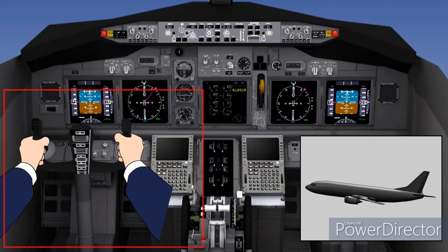The autopilot cannot be engaged on the ground and used for the takeoff. The pilot will be ready to engage the autopilot at some point after the takeoff when the gear is retracted and the aircraft is in a steady climb. It may also be a standard operating procedure to fly the aircraft manually until the flaps are fully retracted. At this time, the pilot will have trimmed the controls to maintain the desired attitude without any continuous stick force.